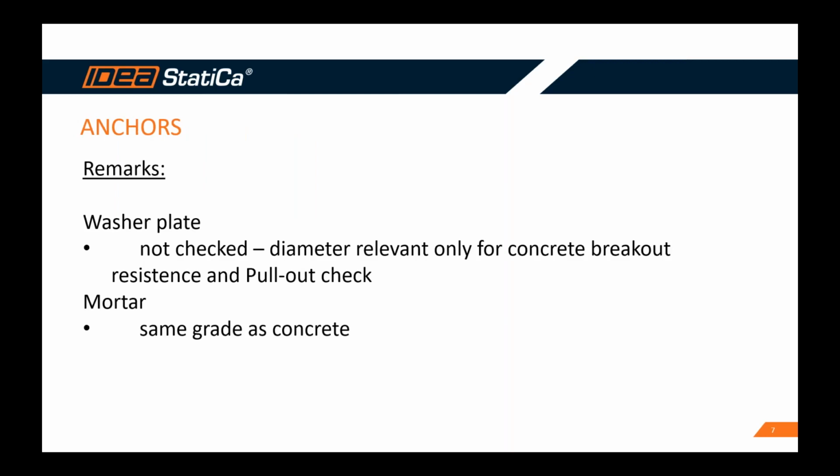About the anchors, I have some small remarks. If you are using mortar between the base plate and the concrete, the mortar has the same grade as concrete, so you cannot make another grade there. It's standard here. And the washer plates are not checked. The diameter of the washer plates is relevant only for the concrete breakout resistance and pull-out checks. So those are small remarks.